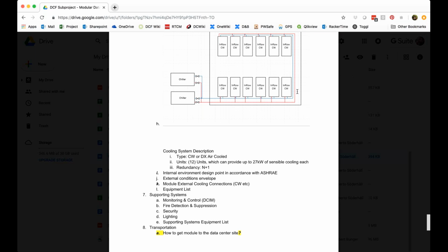No, but if you have chilled water, you can always change the redundancy level. When you have DX, every unit is a single system. You can double up the condensers, but you don't. You have one condenser to each in-row cooler, and they can support them independent of the others. But with a chilled water system, everything is connected to one circuit, or two, if you like.